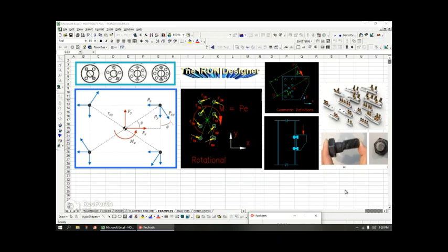Then below that, you can see an example like I showed you before. You had the necking down, and here you see what's going on is you're beginning to go through the process of shear with this bolt by moving the threaded length away from the shank length center line, so their center lines are no longer coincident. And you see the location where the shear is happening. It's exactly in the run out. So if you remember from the previous slide, we specifically talked about the run out being kind of a danger zone to the bolt.